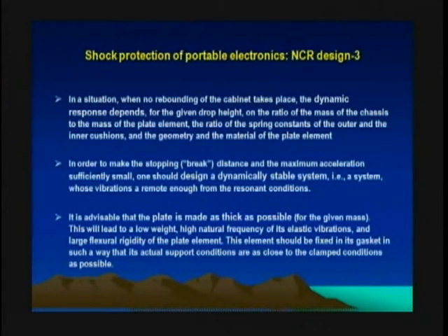So the conclusion was, in a situation where no rebouncing of the cabinet takes place, the dynamic response depends, for the given drop height, on the ratio of the mass of the chassis to the mass of the plate element, the ratio of the spring constant of the outer and the inner cushions, and the geometry and the material of the plate element. In order to make the stopping distance and the maximum acceleration sufficiently small, one should design a dynamically stable system. That's a system whose vibrations are remote enough from the resonant conditions.